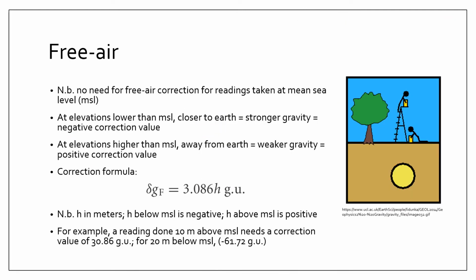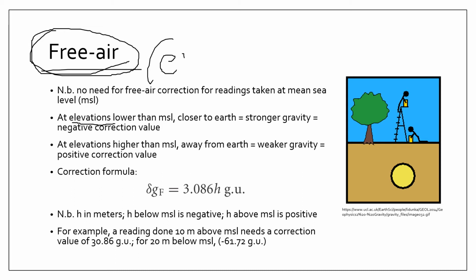Now, let's talk about the other correction, which is the free air correction. So this accounts, in layman's terms, free air correction is just about the elevation. All right, but in the gravity survey jargon, they use elevation correction to describe free air correction plus the Bouguer plate correction. Okay, so we are stuck with this free air correction term, but to laymanize, this is all about elevation.